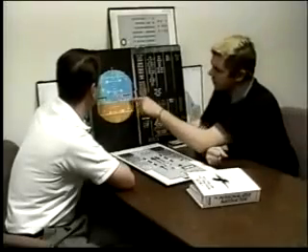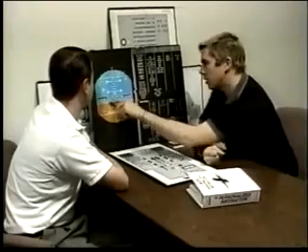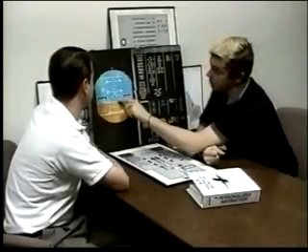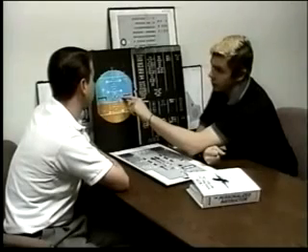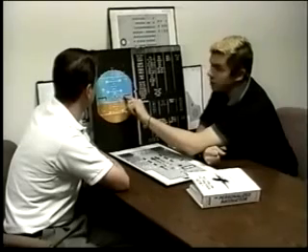Right now, this is telling us that it wants us to be in a right bank, and because it's above the horizon line, it wants us to climb. Well, actually, because it's above the flight path vector is the climb that's going on. Okay, so this is telling us to pull up and turn right.